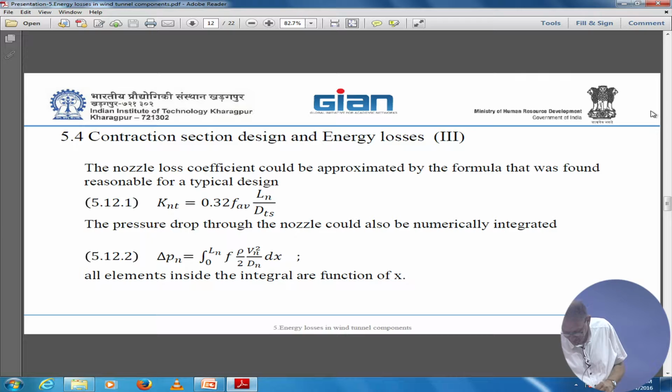At least 6 to 9 again, preferably 9. It means the honeycomb will let through only eddies or vortices of the size of the cells. So it will kill any bigger disturbance than that. It will decrease the size of eddies, and consequently it will reduce the disturbances to a lower level.